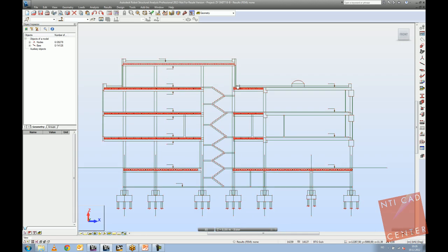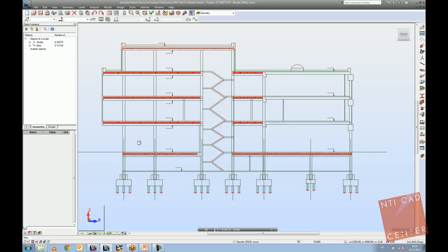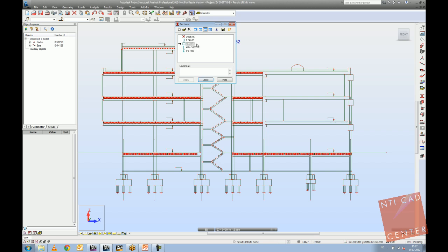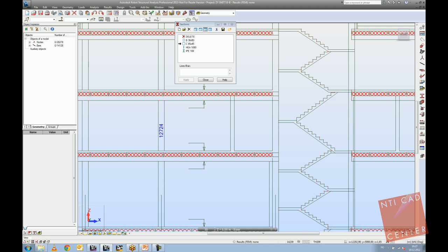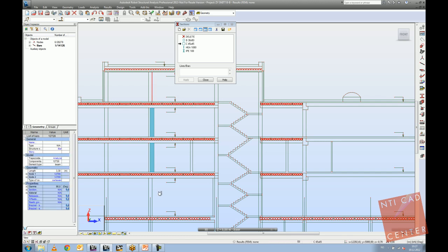But again, for example, if I would have a central axis of these columns, I could easily make structural elements out of them because it's already a bar. What I just need to do is specify, for example, a section size. We'll enable the sections, and once I click on the element list, for example, I can select several at once.